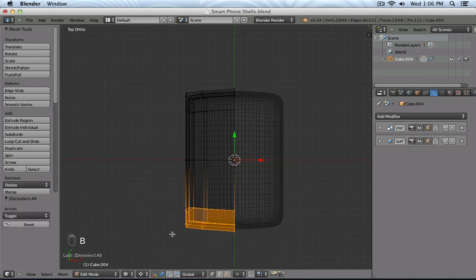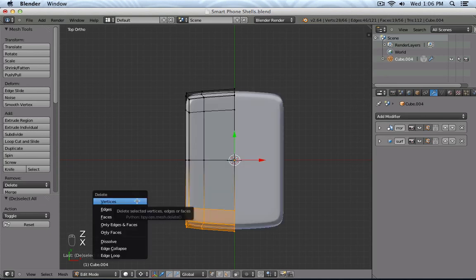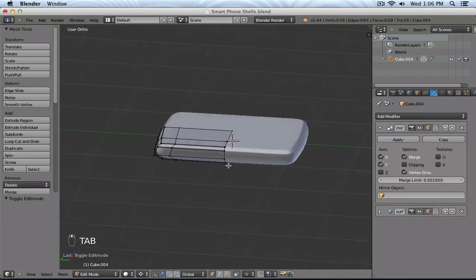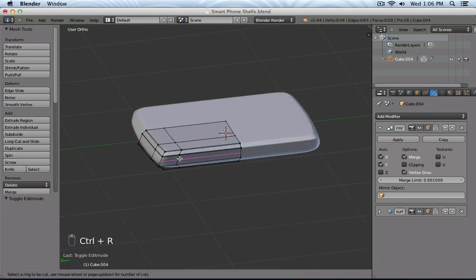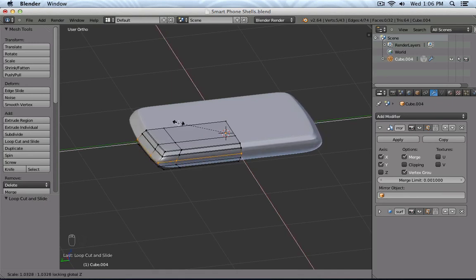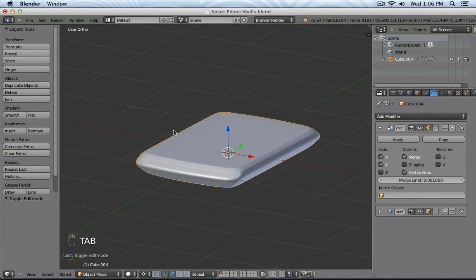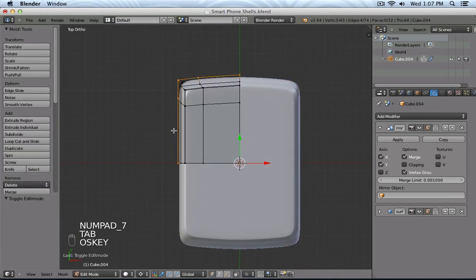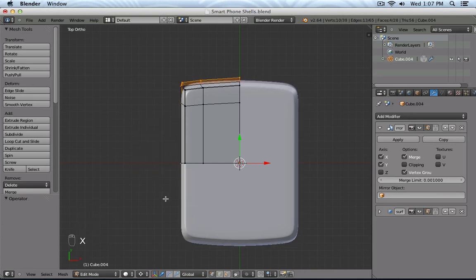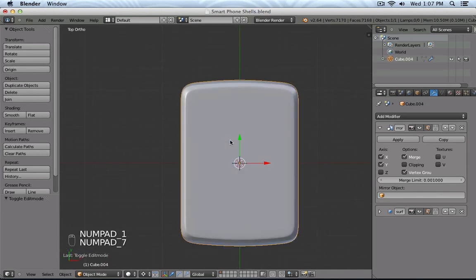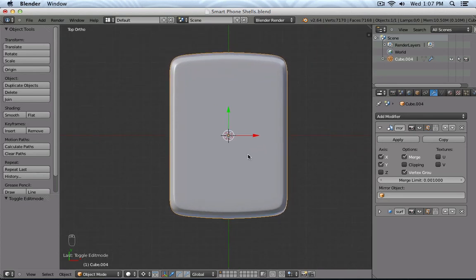Then I can select this edge or all those vertices and simply delete them. And then turn Y on. And now I have a model where, for example, all I need to do is work on 1/4 of my model. And then Alias is, and Blender is actually, with the modifier, updating all the other 4 corners for me. So instead of, for example, working on the complete model, here I only work on a 1/4 part of my model, and that saves me, in case it's a very symmetrical object, for example, a lot of click jobs. So that's the way how you use the mirror modifier.